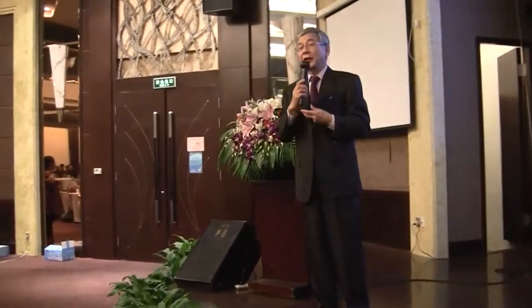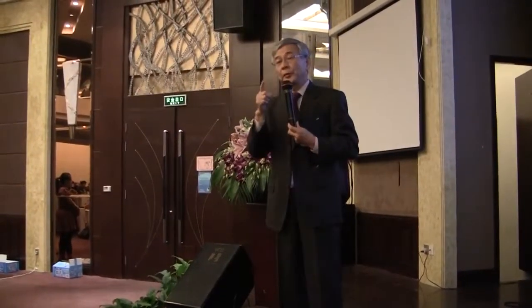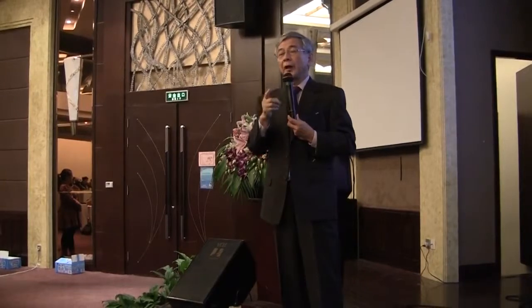I think it's beyond our ability. As in the ordinary concept design, Dr. Yoshioka also discussed the freeze valve reliability and the time to drain the fuel salt into the drain tank. It depends on the freeze valve. So we have to take into account improving that, so that the fuel salt can go down to the drain tank as soon as possible. It may be our problem to solve.